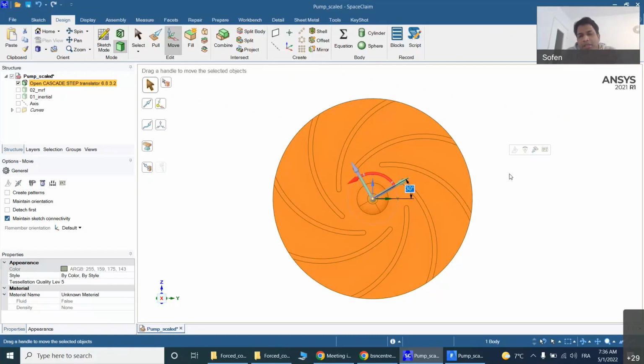because the blade is rotating in the physical sense, but here for computational effectiveness, we assume the static position of the blade and rotate the fluid across it. If you have a sufficiently higher number of blades, like 20, 30 blades, that's fine, because even if rotated 20 degrees, 30 degrees, it is going to be isometric, a rotational symmetry kind of thing.